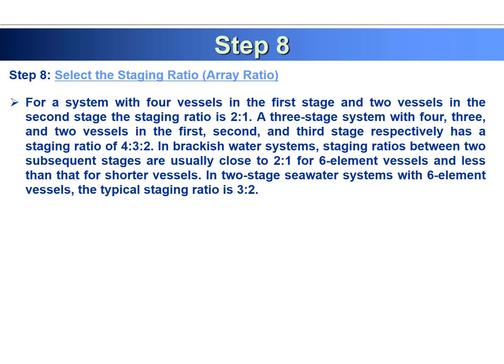So depending on how many pressure vessels you have, we can select a 4:3:2 ratio, a 2:1 ratio, or a 3:2 ratio. So depending on your recovery and your pressure vessel number, we can decide how many staging ratio is required for our system.